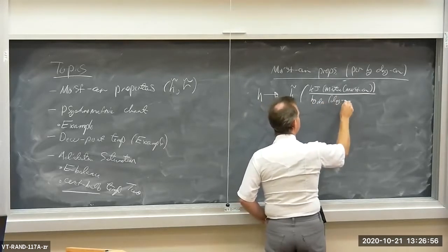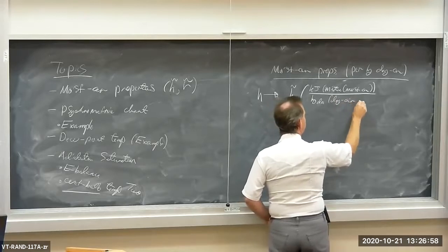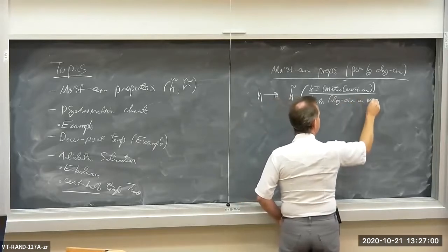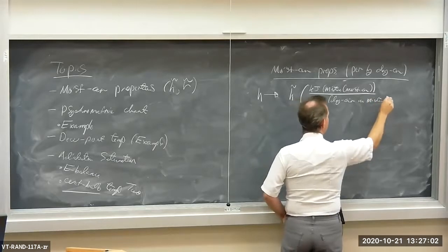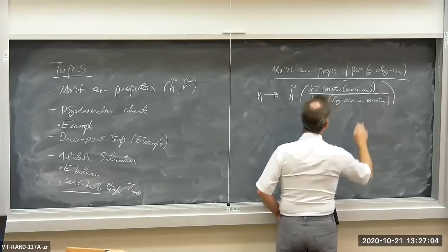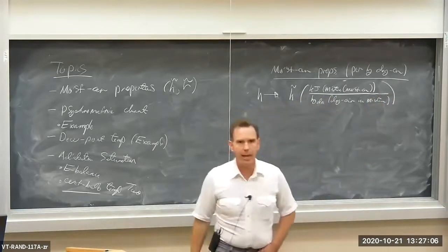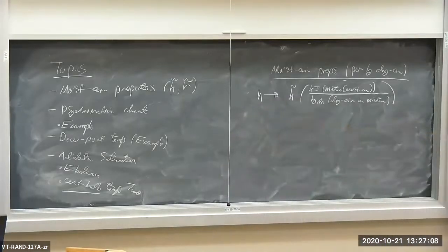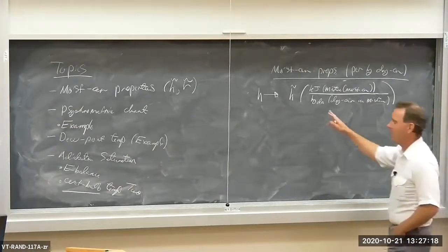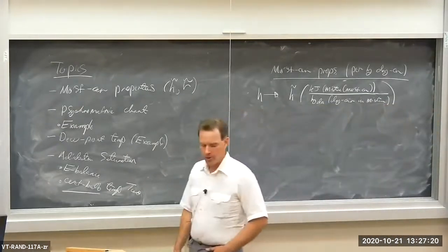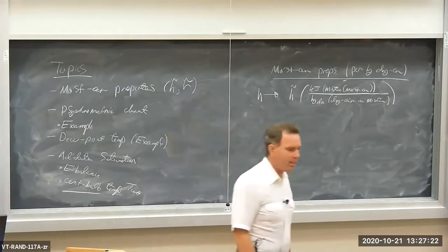It refers to dry air in mixture. Okay, so when you see the tilde over the h, that means kilojoules per kilogram of dry air in the mixture, okay? So instead of per kilogram of mixture, it's per kilogram of dry air in the mixture. So that makes the problems a little bit easier to solve.